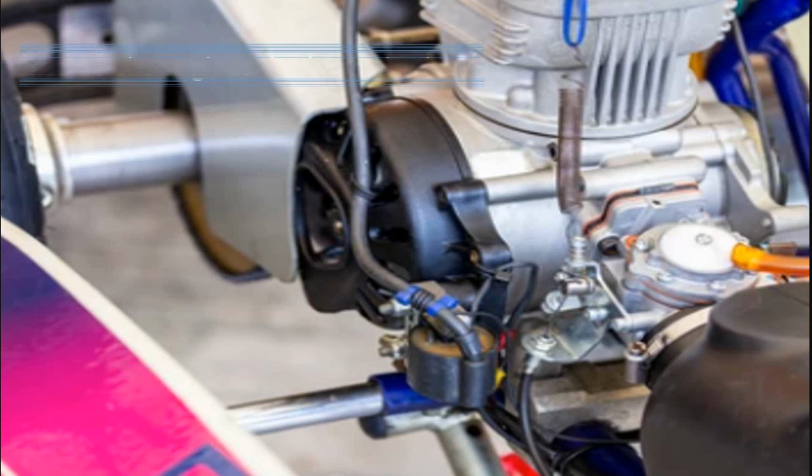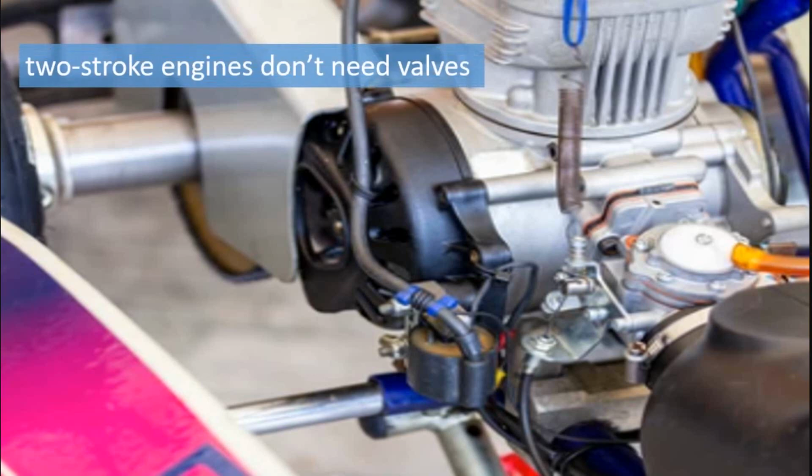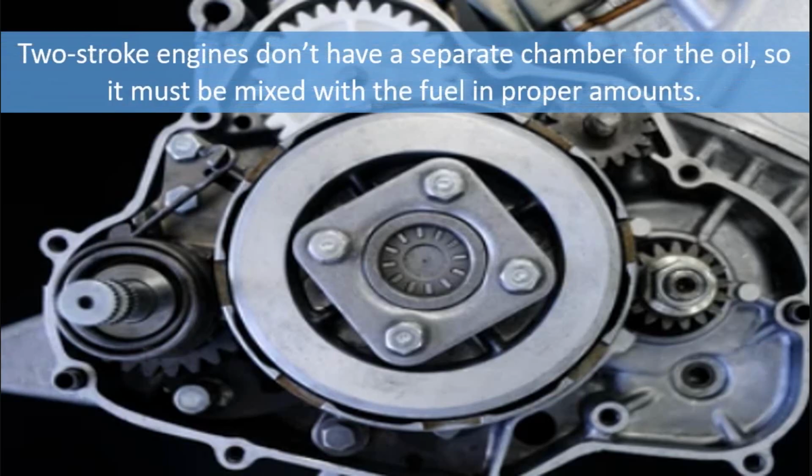Another difference is that 2-stroke engines don't need valves because intake and exhaust are part of the compression and combustion of the piston. Instead, there is an exhaust port in the combustion chamber. 2-stroke engines don't have a separate chamber for the oil, so it must be mixed with the fuel in proper amounts. The specific ratio depends on the vehicle and is found in the owner's manual. 2 of the most common ratios are 50:1 and 32:1, with the 50 and 32 referring to the amount of gasoline to 1 part of oil.